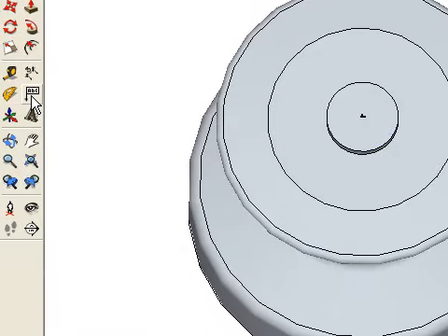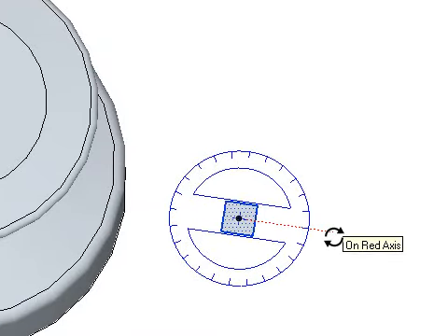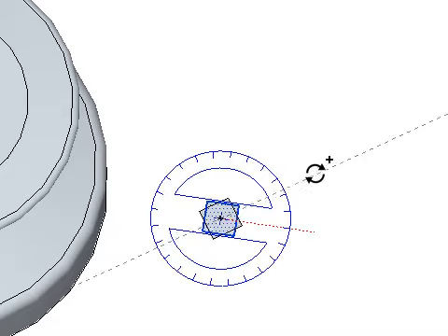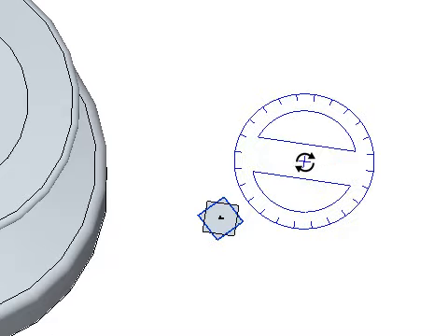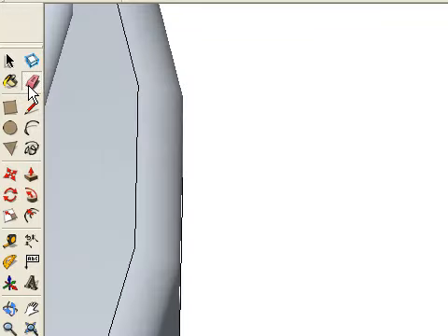So now I have the opening for the winch handle and the position for it, but the winch handle has kind of a star shape. I'm going to form that by doing a rotation and a duplicate. So I hit Control, that makes it a duplicate. I go to 45 degrees, and there's basically my section.